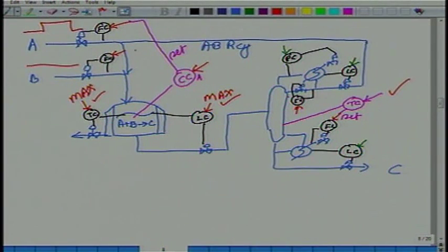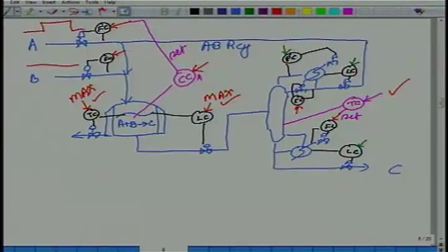Therefore, that extra A has built up in the reactor, and the reactor composition has gone from, let us say, 10% A to 40% A. But after the pulse has been withdrawn, the two feeds are still stoichiometrically balanced. So you can operate it at 40% A, 10% A, similarly 90% A. As long as the composition controller is on, stoichiometric balancing of the two fresh feeds will occur automatically. Does that make sense or no?